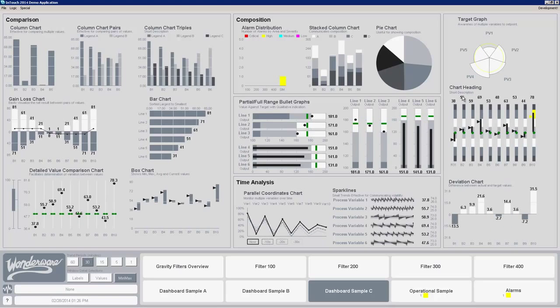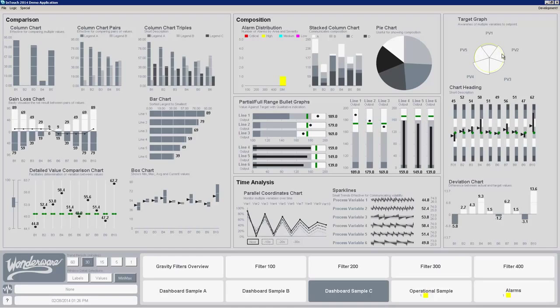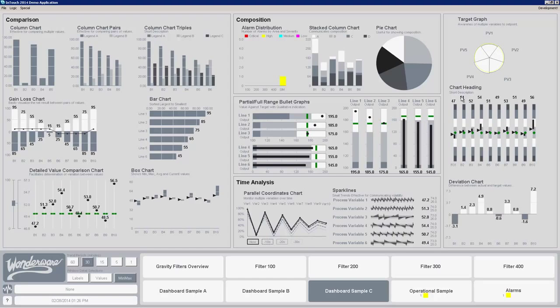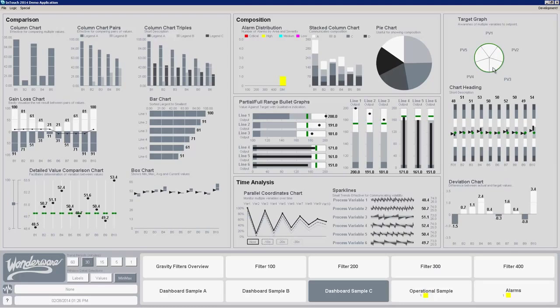What happens is that if I'm on process, or in range of where I'm supposed to be, I just look down and I can see everything as a circle. I've even set this up so that when it gets within a certain tolerance, it'll just go to a green circle. If I see anything other than that green circle, I can assume that I probably need to look at something a little bit more closely to find out why it's not where it should be. And now it's within tolerance, so it's showing the green circle.